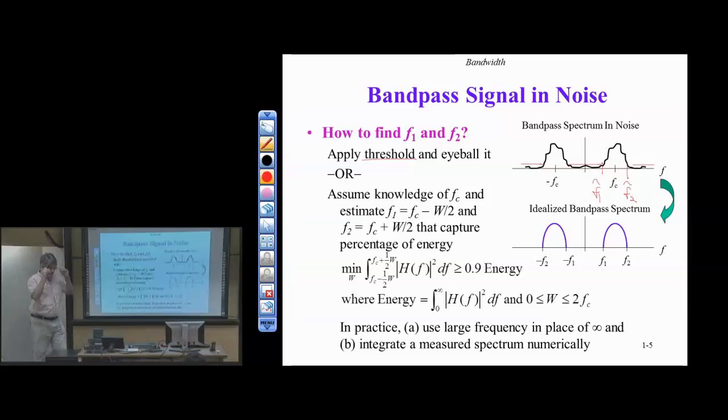When we had bandpass signals like this, if we were to want to sample it, we would just take the upper end, like F2? And say we sample at least at 2 times F2? Correct. That's correct. So the standard sampling theorem says, again, that the sampling rate has to be greater than 2F max. Now, in this case, F max is going to be F2. Now, there's another version of the sampling theorem called bandpass sampling, which we will talk about really not until March 2nd, or March 3rd. It's coming. Okay, so there's a way that we can reduce that sampling rate dramatically.